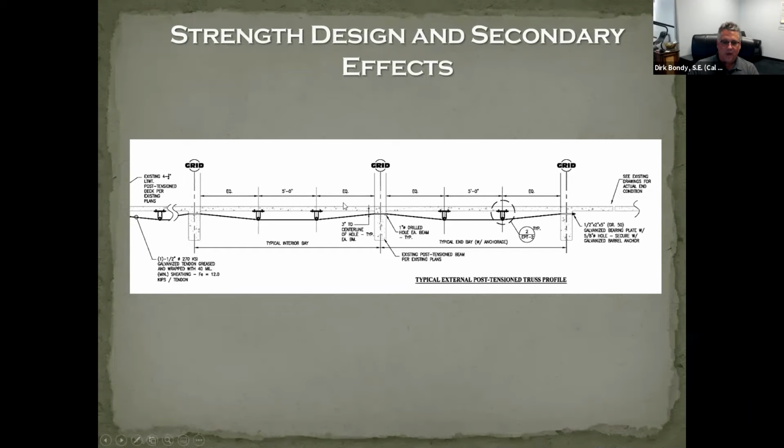So your final pre-stressing forces from your balance loads, subtracted from the primary pre-stress moments, F times e, give you the secondary moments, if you recall your pre-stressed concrete class. The primary pre-stress F times e is substantial when we come in below the structure. So you really have to understand and make sure you're accounting correctly for secondary moments as you are externally post-tensioning a structure.